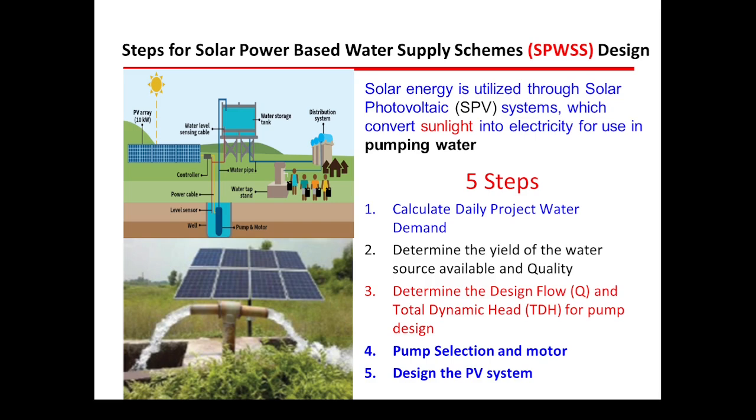And step number 3 is to determine the design flow and the total dynamic head for pump design. Here I mean that you should consider your project daily demand.